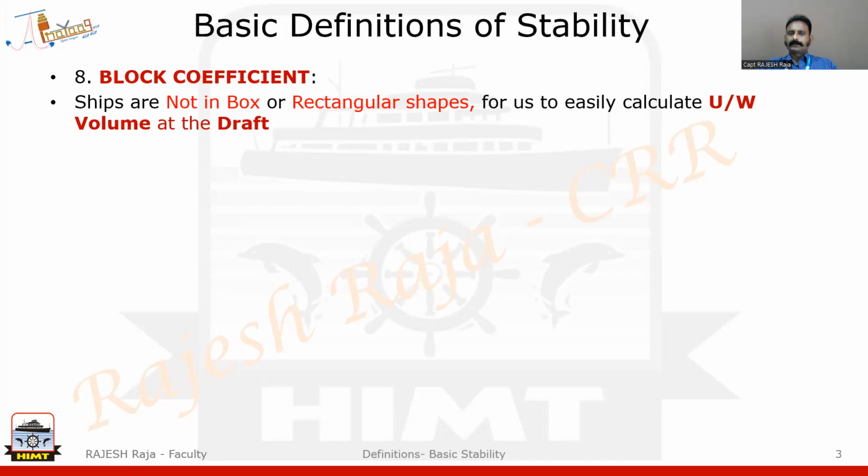Now, most of the stability calculations, if you agree with me, one of the important parts of calculation is the calculation of displacement. We saw earlier how you can calculate displacement using your flotation principle, where one of the important parts of the displacement calculation was underwater volume. So again, here also, I need an easy method to calculate the underwater volume at any particular draft.